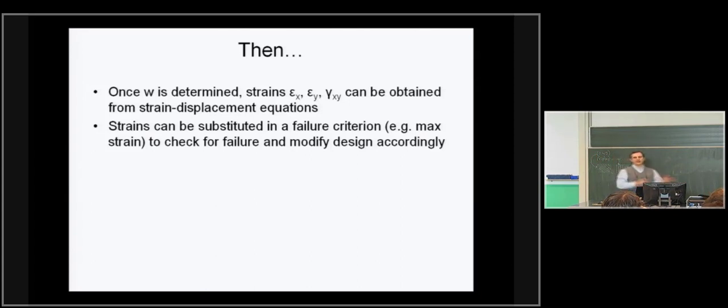And that's not even half the story. I have to translate these displacements into usable strains through the structure, which is mostly what you are doing in your homework 1 right now. So I make the W's into strains, and once I have strains, I can then either use them in a strain-based criterion or translate them further into stresses if I want through stress-strain equations, and use a stress-based criterion, and that will give me an indication of which ply fails.